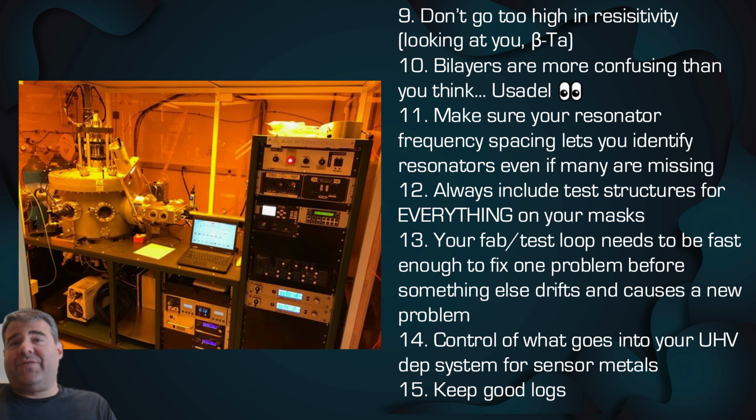Control what goes into your UHV deposition systems for sensor metals. You really need to control your metals. That first metal layer, the sensor layer for the MKID, is just really important. And finally, good practice for everyone, keep good logs.